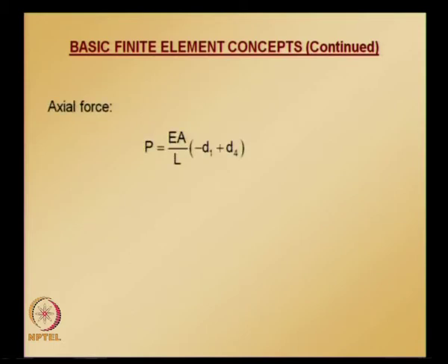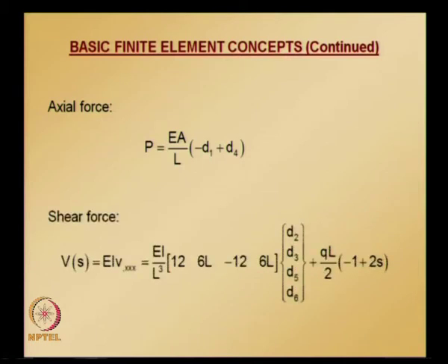For that kind of element, using the computed degrees of freedom, we can find axial force in the frame element and also shear force. And since this frame element is subjected to distributed load, we need to apply fixed end correction, and S goes from 0 to 1, S is equal to 0 corresponds to node 1, S is equal to 1 corresponds to node 2.